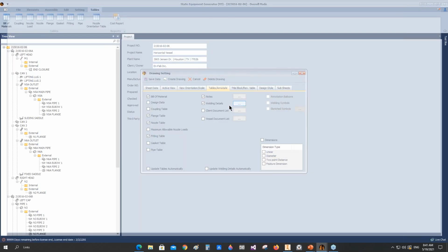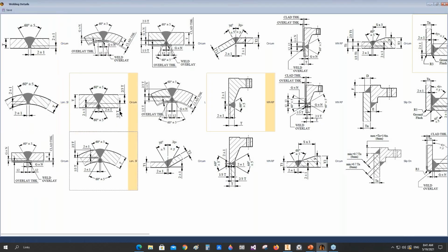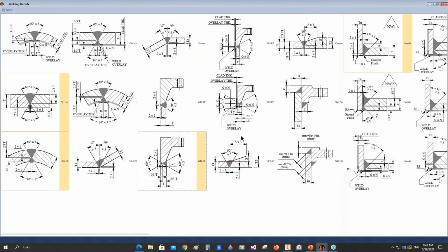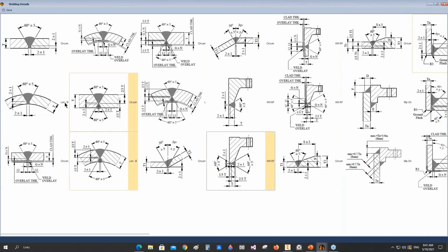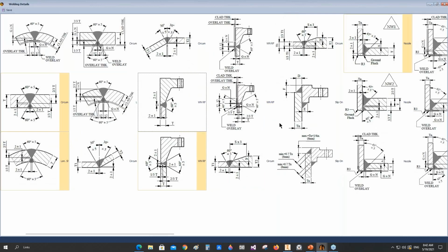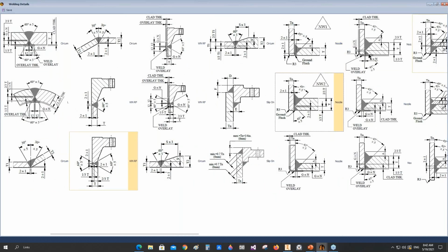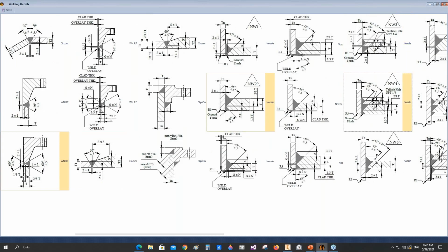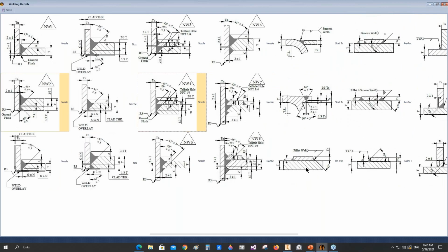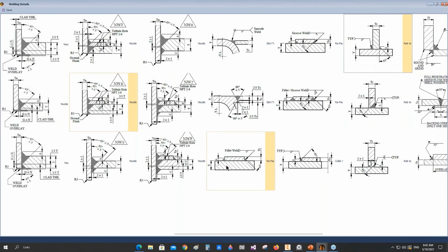The welding details, let's select other welding details because the thickness here is, I think, more than 20 millimeters, so we will make it double V instead of single V. So we will select this, and it's the same for flanges and some other attachments. The nozzles with reinforcement pad detail, for the saddle wear plate and the saddle whip.